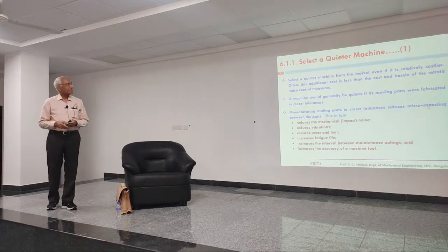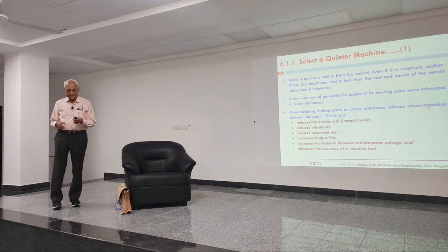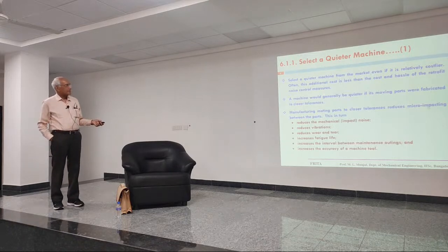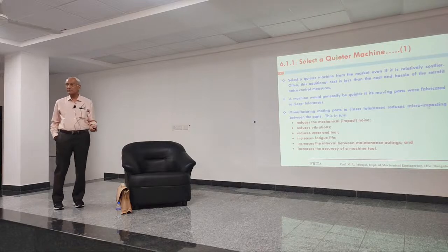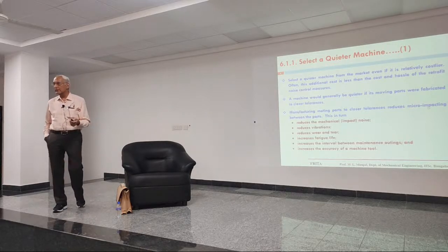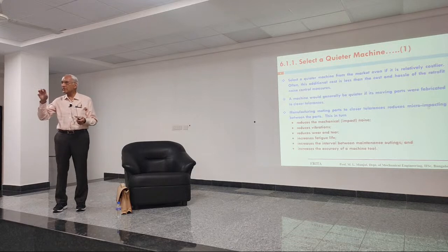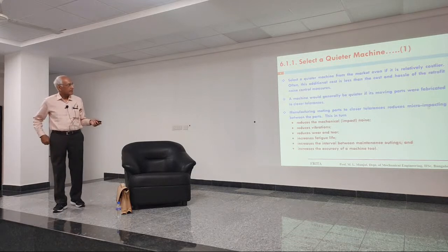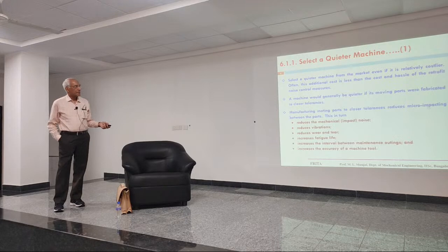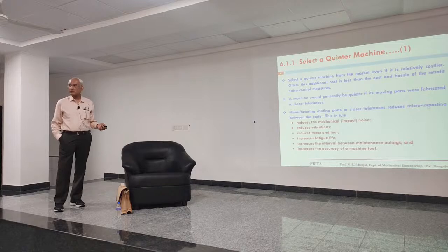Can I select a quieter machine? What does that mean? Select a quieter machine from the market even if it is relatively costlier. Often this additional cost is less than the cost and hassle of retrofit noise control. Whatever you try to do later will turn out to be much costlier than spending a little extra money in the beginning itself. A machine would generally be quieter if its moving parts were fabricated to closer tolerances.